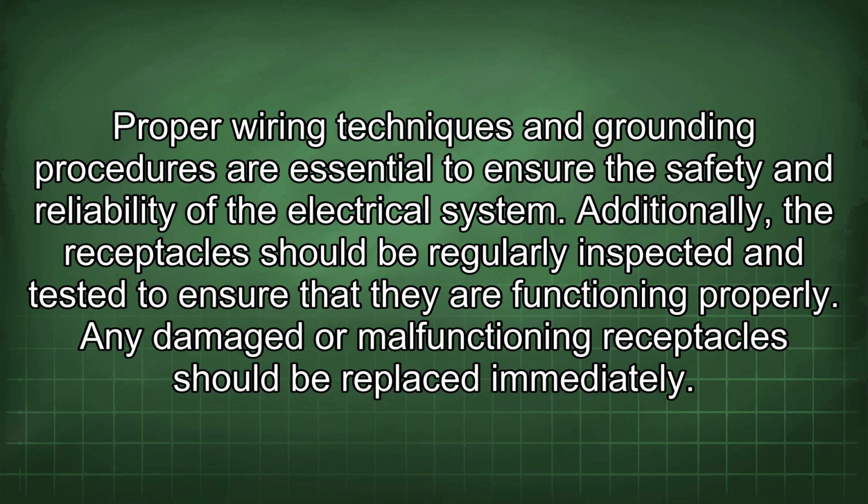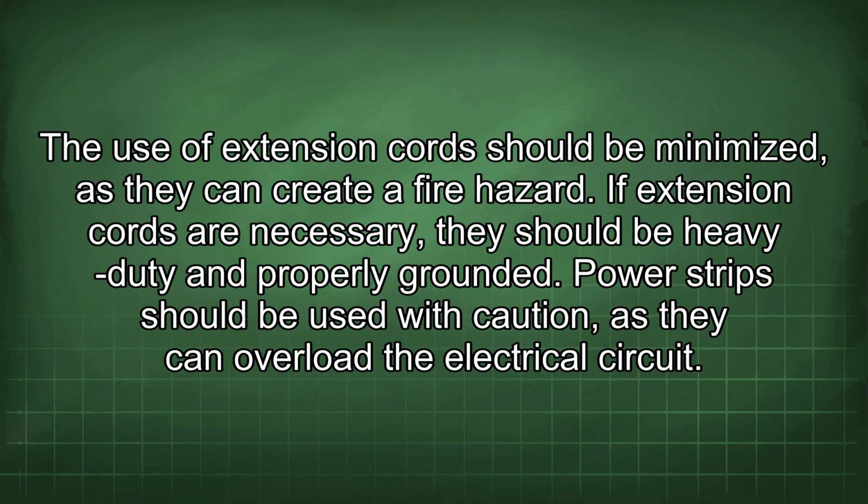Any damaged or malfunctioning receptacle should be replaced immediately. The use of extension cords should be minimized, as they can create a fire hazard. If extension cords are necessary, they should be heavy-duty and properly grounded. Power strips should be used with caution, as they can overload the electrical circuit.